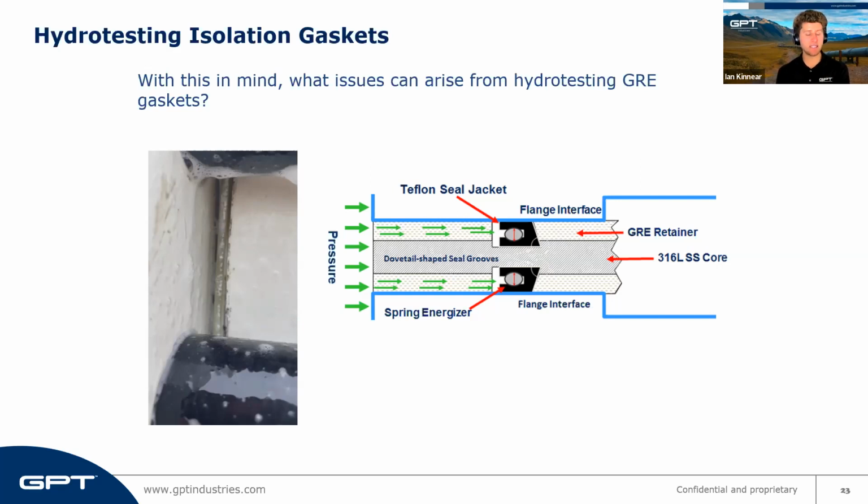When you use an ID seal or an isolation gasket with no permeable material, you can hydro test and you're not going to change these dielectric values in any way. So it gives the most confidence to put the isolation gasket in, hydro test with it, keep it in, have actual measurements of the system that you're hydro testing, and not lower the values. So it's just something to think about. It's something to be aware of.